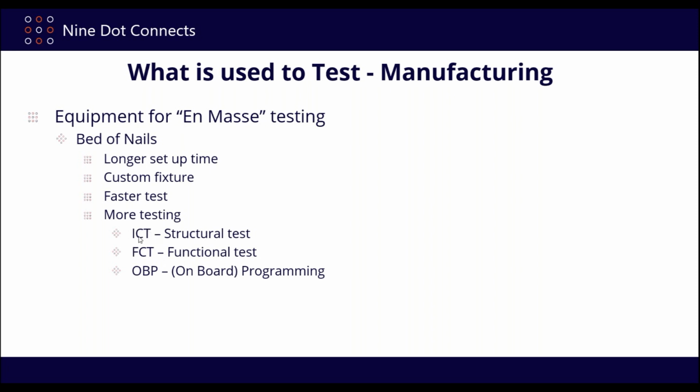Now, the ICT, when they say ICT, they call it an in-circuit test, but when I went and looked a little bit further into this, what they're saying is that this is kind of what they call a structural test, which effectively, again, is a continuity test, which we just talked about here. So it is looking for what I'll call structural issues as opposed to functional or even programming here. But what this can do is it can actually program things on the board.